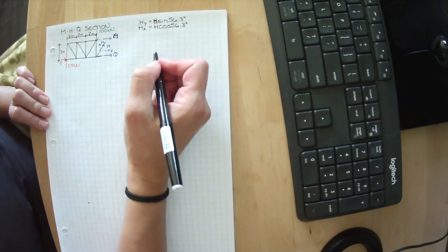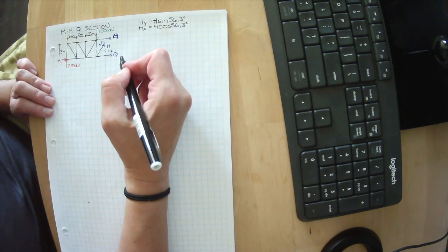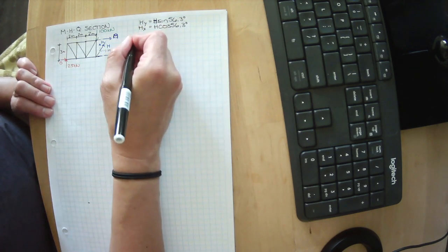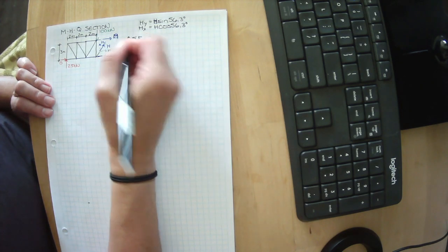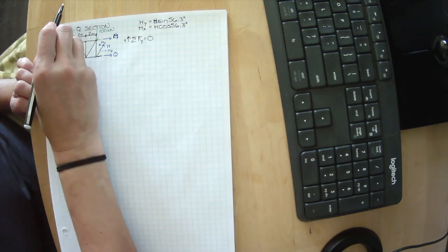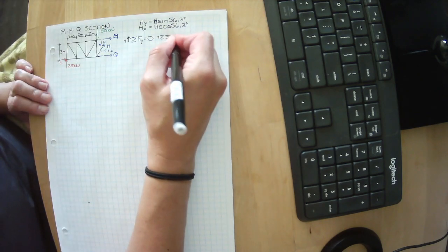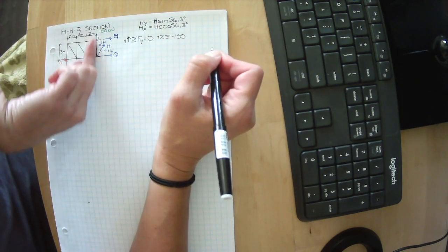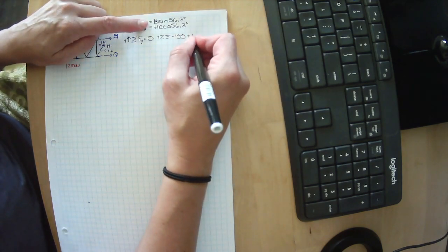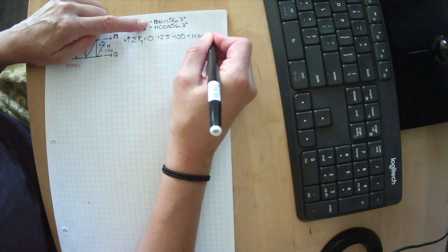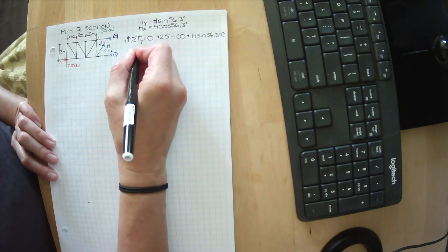So we can go through and start solving this now. Let's solve for our forces in the y direction. So the sum of the forces in the y direction equals 0, where everything upwards is positive. We have 25 kilonewtons going upwards. We have 100 kilonewtons going downwards. And we have HY going upwards. So plus HY, we know that HY is H sine 56.3 degrees. We can solve for H.